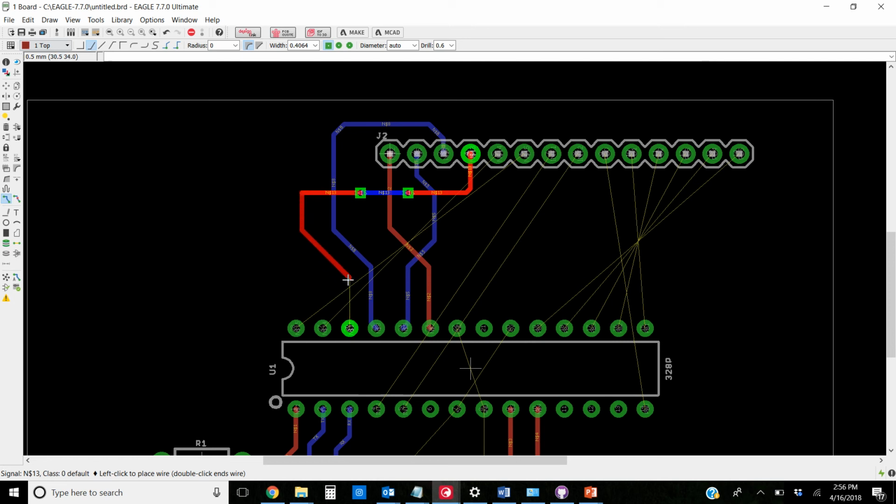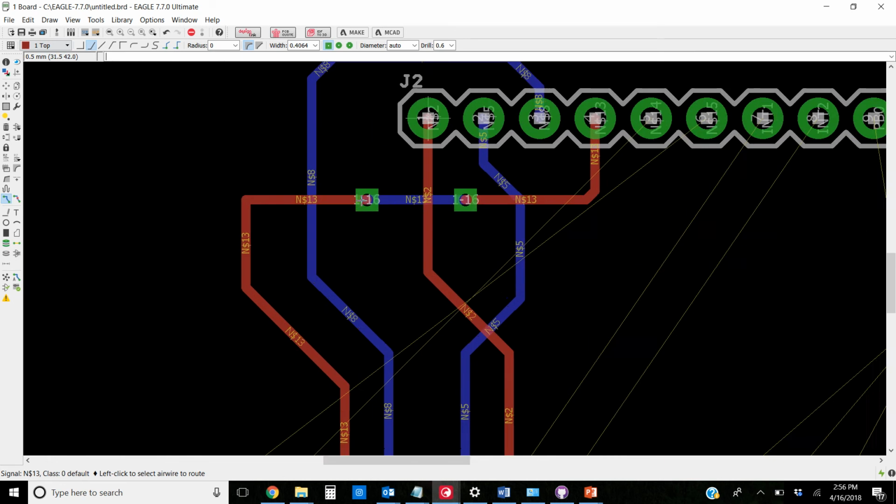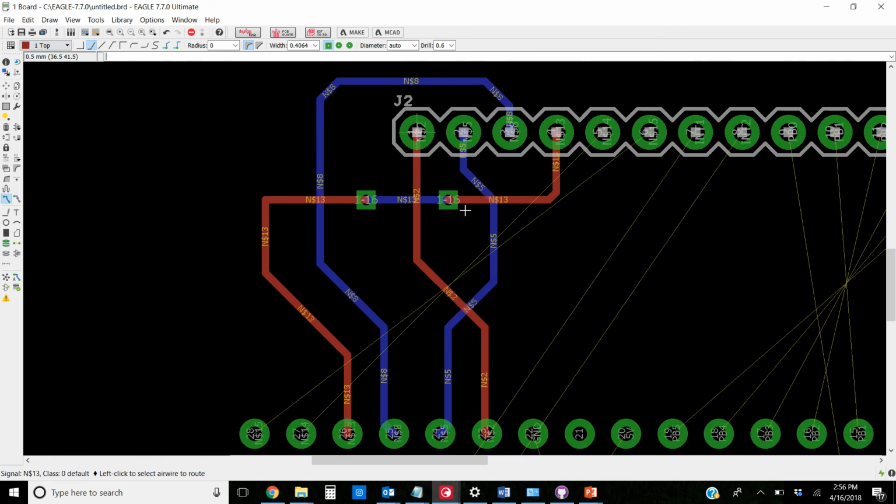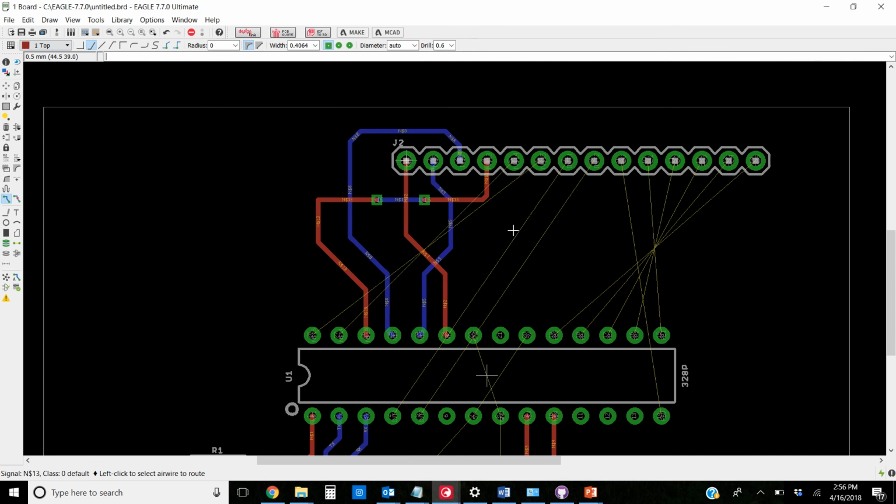And then I can bring that trace around, and these squares here are actually now vias. So this was a way to cross multiple things. This wasn't the most elegant way to do this, but it shows you how you can use vias to navigate. So again, left click, bottom, but again I get stuck, so I'm going to hit back to top, and then back to bottom, and I can do that as many times as I have to traverse all of the different layers.